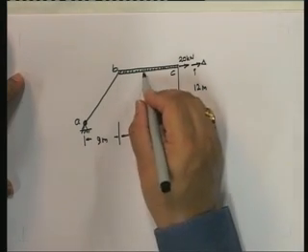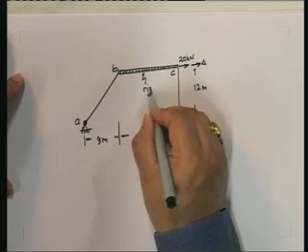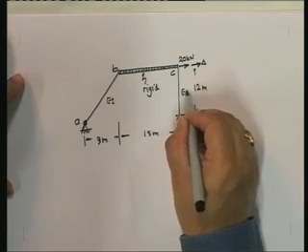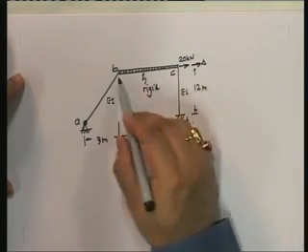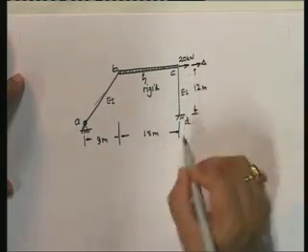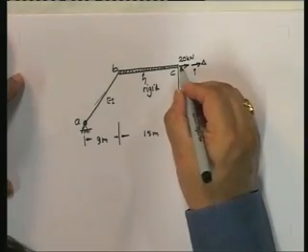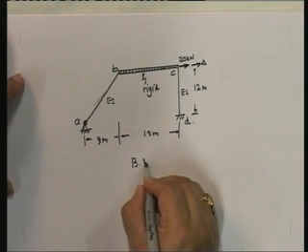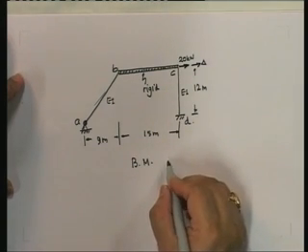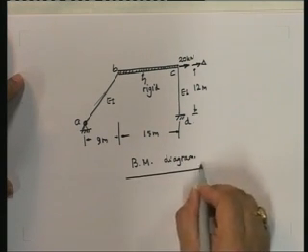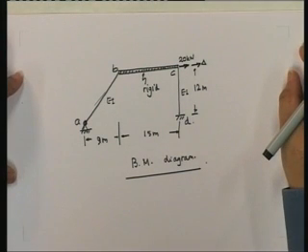For BC, it is rigid. This is EI and this is also EI. This is totally rigid, flexurally as well as axially. These are actually rigid but flexurally flexible, so is this one. Okay, and this is being subjected to this load, and the question is the bending moment diagram. That is what has been asked today.